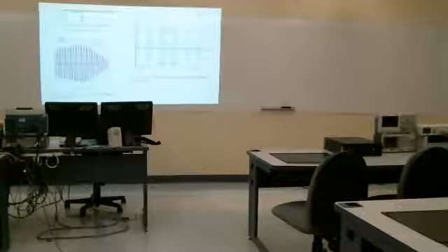So now our modulated waveform, if I multiply the cosine through here, I'll have A cosine 2 pi FC of t plus x(t) cosine of 2 pi FC of t. Well, this is my double sideband modulation, right? Multiply x(t). And what that does is just translates the spectrum in frequency.